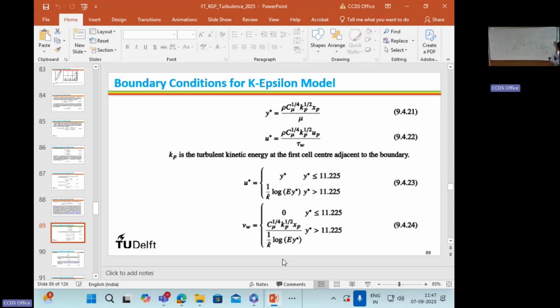Maybe flow at this here. You need the tangential component velocity, this velocity minus this velocity divided by the distance, into shear stress. That time you can use the viscosity of the wall that is stored at this location, right? If you are calculating shear stress at this point, you will use the viscosity value that is stored at this location, right? To solve the transport equation, you use the eddy viscosity stored at which location?